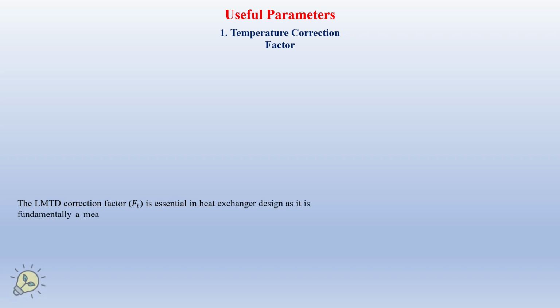Useful parameters which are to be considered in the thermal design of heat exchangers. We will start with the temperature correction factor. In fact, this factor represents the deviation from the ideal conditions for the actual temperature profile in the heat exchanger.